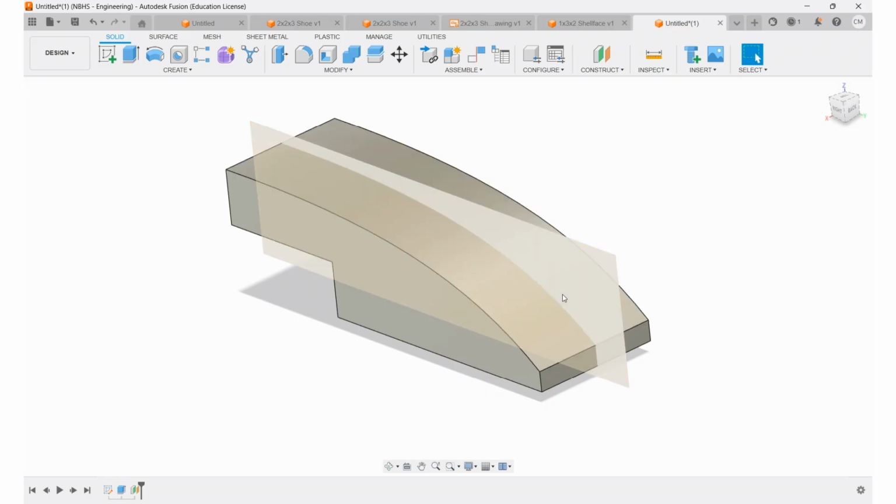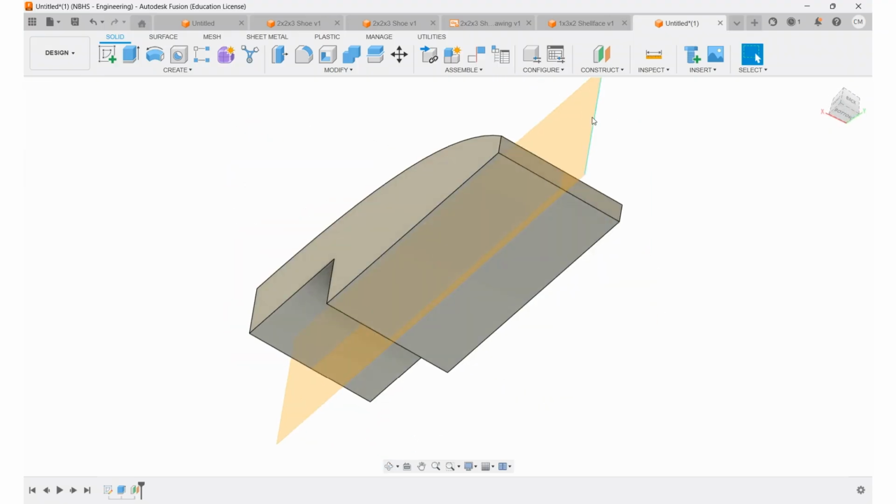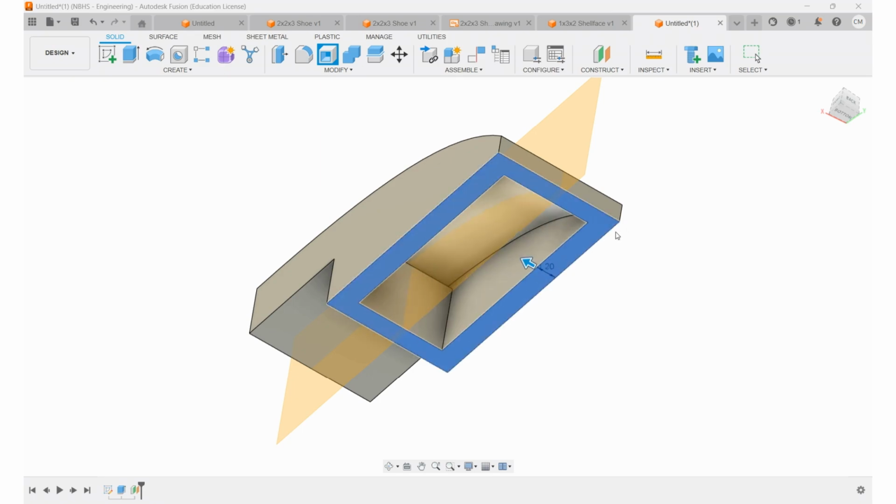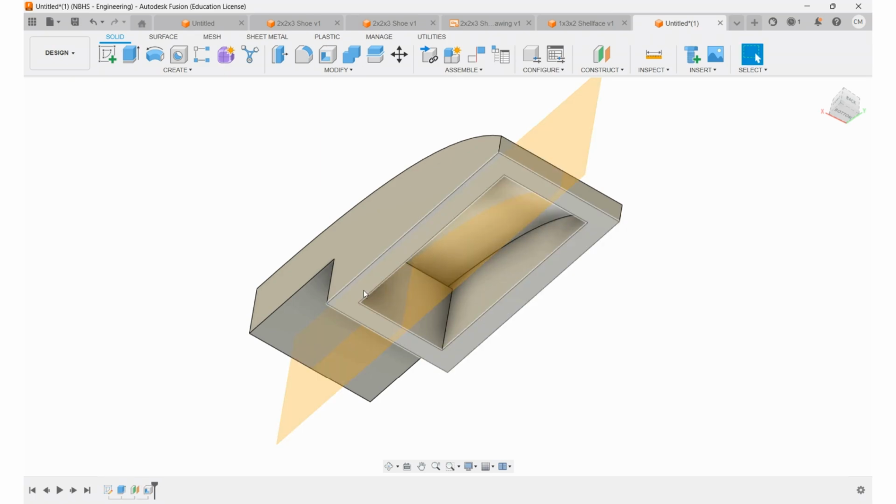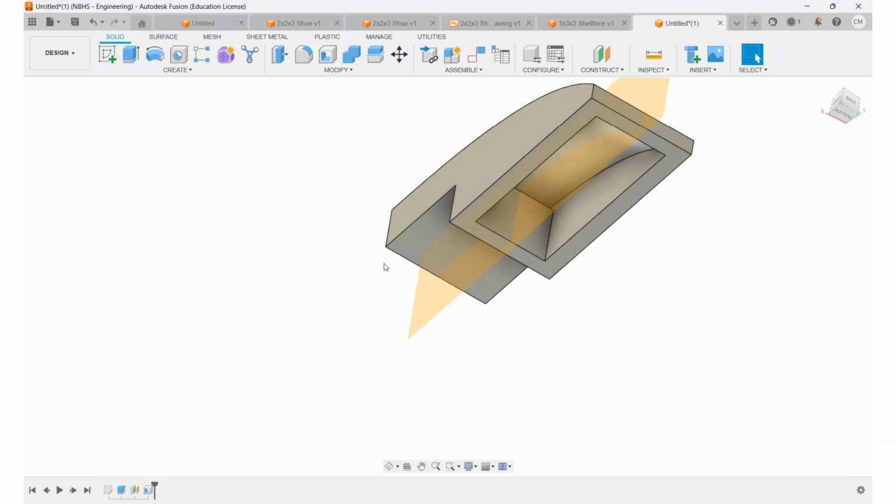All right. So I don't have any studs to model on top. So that means I can skip to our next normal step, which would be to go ahead and put a shell in here. All right. And I'm going to go ahead and put that 1.2 millimeter shell in here. And you'll see that it didn't do what I want. The bottom of this thing should be shelled here, and it should be shelled here.